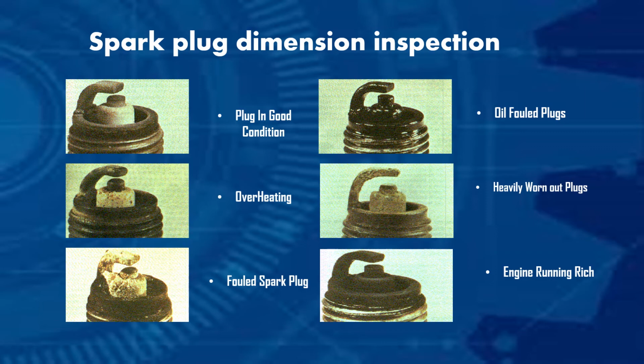A fouled spark plug indicates a low cylinder compression. This leaves unburnt residues on the plug due to a lack of cylinder efficiency, such as when oil and lead were used. This may lead to running on, as the plug heats up and is capable of combustion alone with no spark. An old fouled spark plug shown indicates a serious engine oil control problem, probably not compression rings but oil control rings or valve guides and seals.